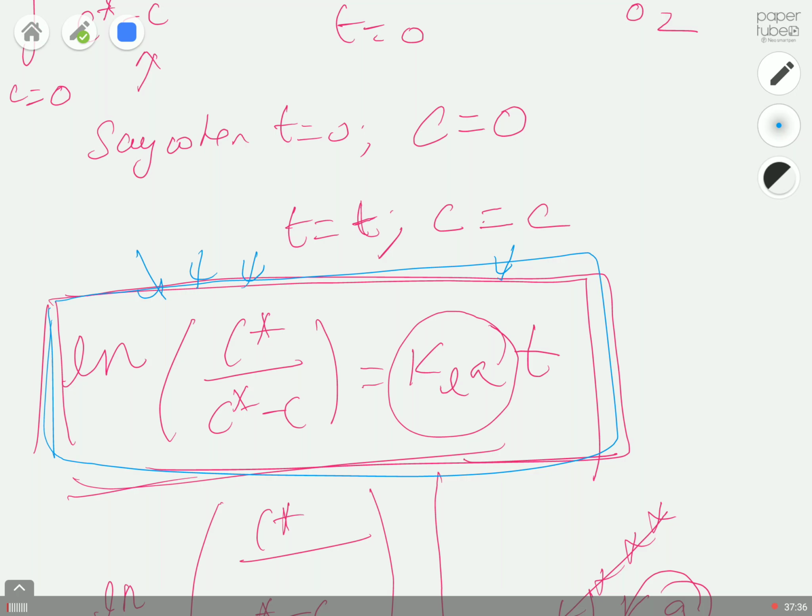Even if you start from zero oxygen concentration, the maximum solubility is only 7.7 milligrams per liter. So if you take the difference, 0 minus 7.7, that's equal to 7.7 milligrams per liter. So the concentration gradient is very low, which means the driving force for the oxygen to transfer from the bubble to the liquid is very low.